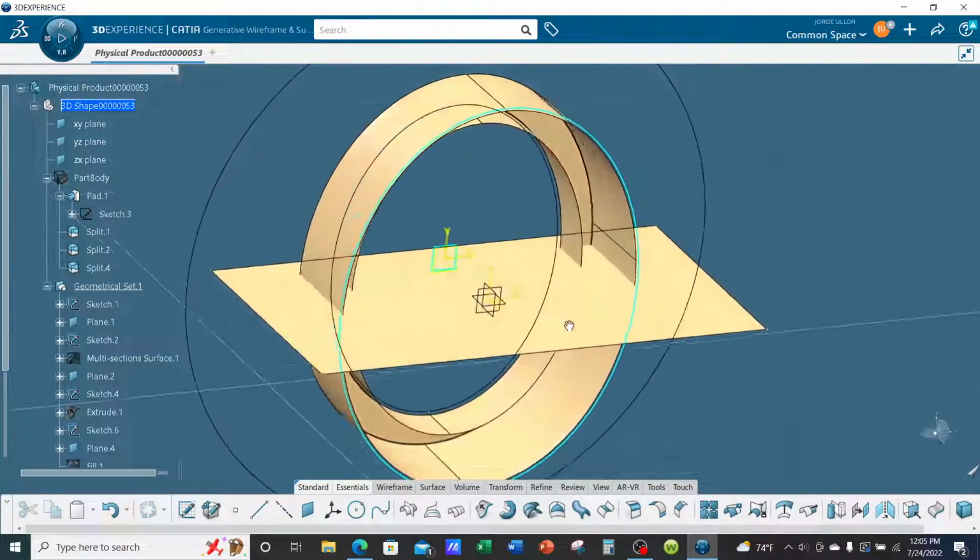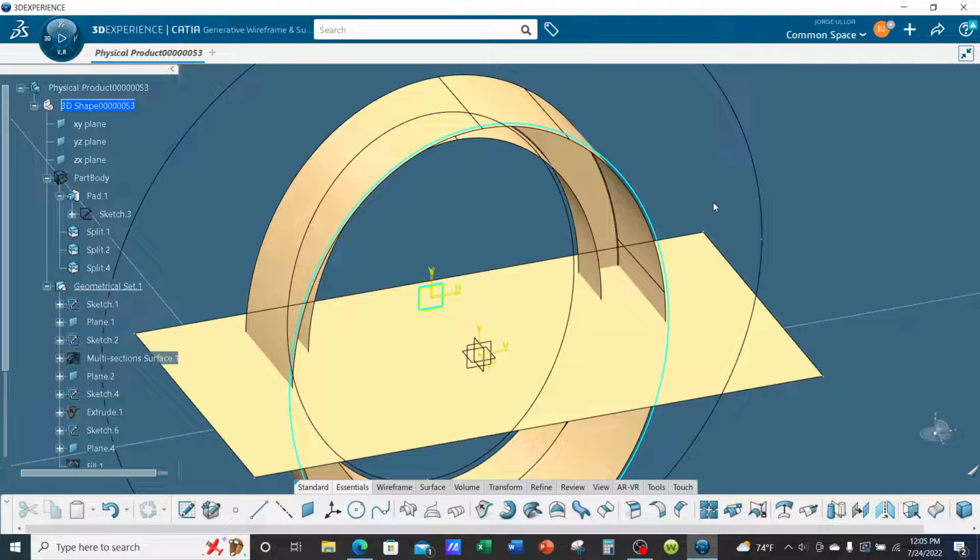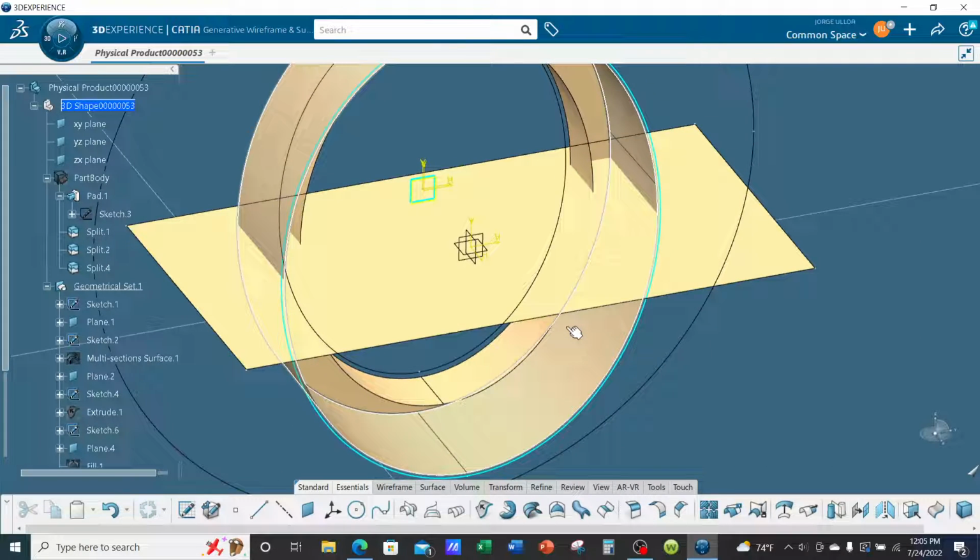Okay, so we're going to take our existing joined surfaces and now we're going to offset outward 1/8 of an inch. So how do we get 1/8? It's 0.5, so currently it has an offset of 0.5. And we're going to change the thickness on the lower portion of the frame to 0.375. So if you take 0.5, subtract 0.375, you get 0.125, which is 1/8 of an inch.